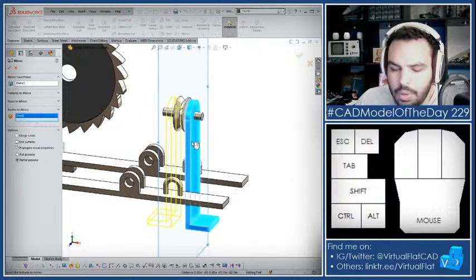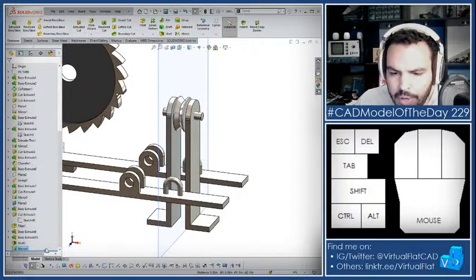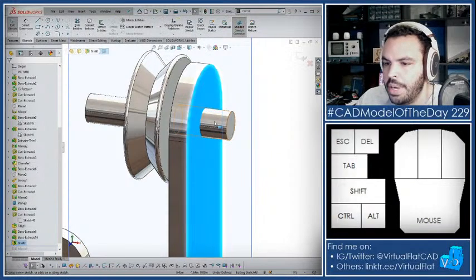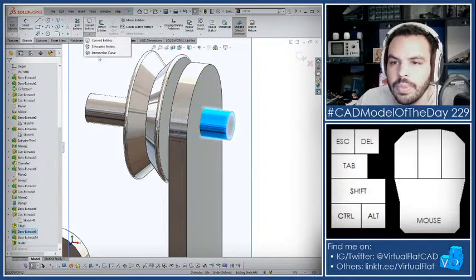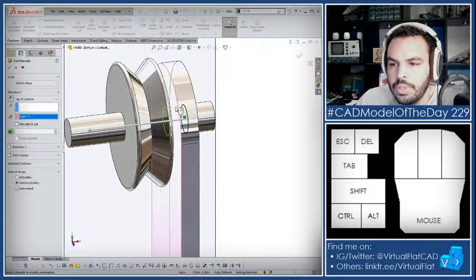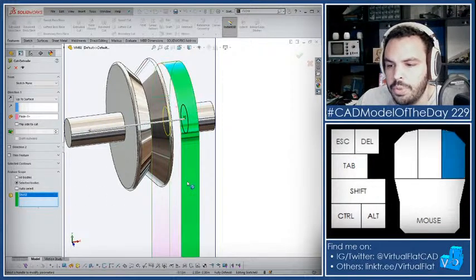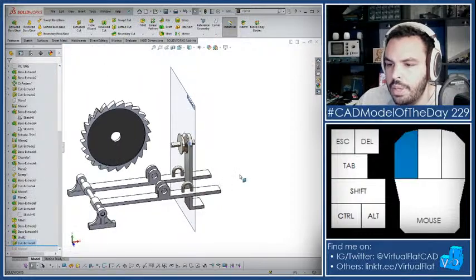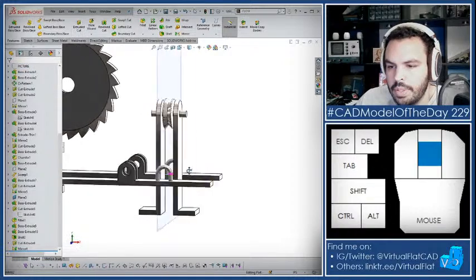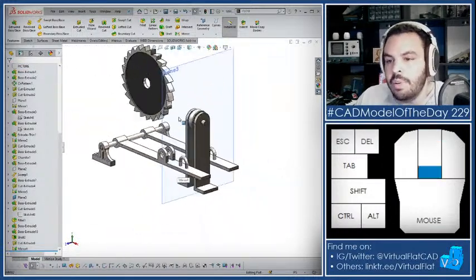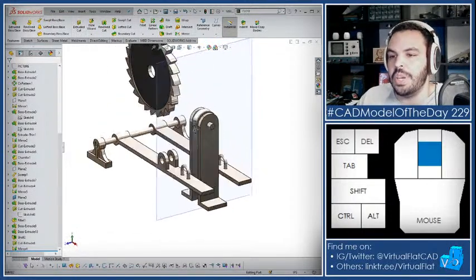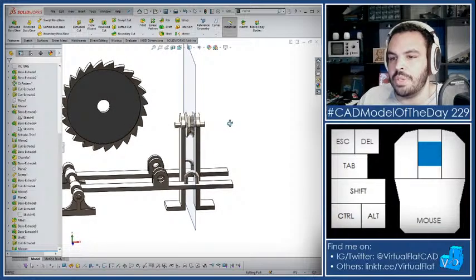Body, I'll just, oh yeah, mirror bodies. Yeah, I can just do that, but I forgot to punch the hole. The only thing is that you have to leave the hole as a separate operation. I can say intersection, extrude cut, up to surface. Make sure it's only affecting this body. Right click, hit OK. There we go, something like that. And now immediately it's a lot easier to tell what's going on, or what's supposed to be going on, with this image.